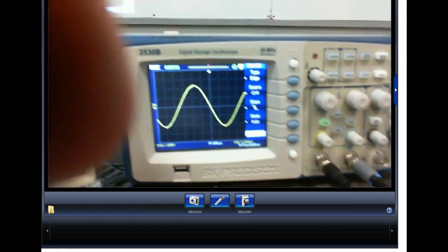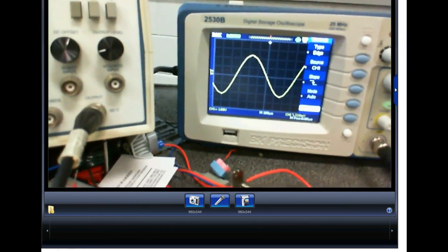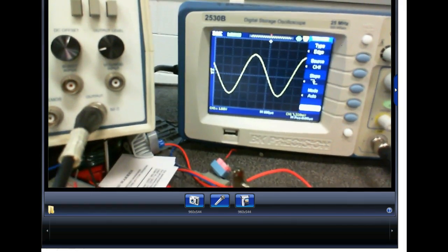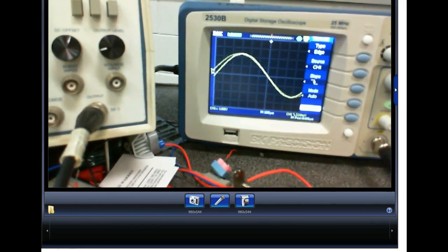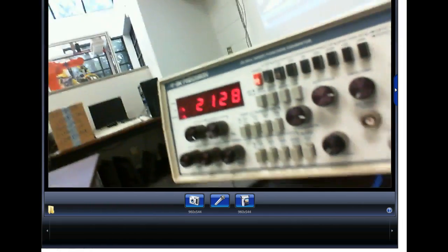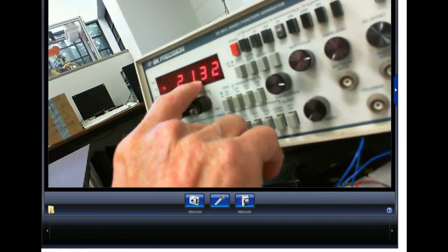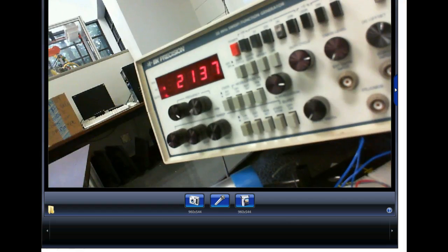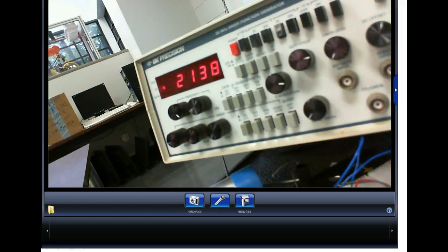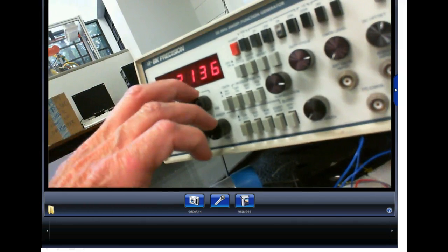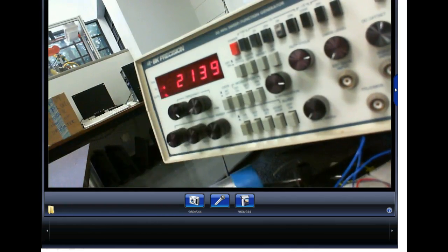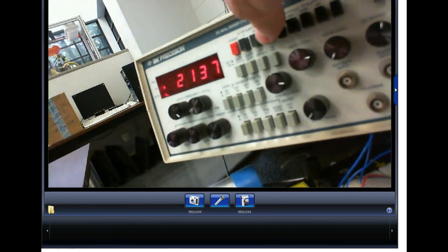But you notice the oscilloscope changes instantly. So you can see it change instantly. But the frequency generator is okay. I wish we didn't buy them with these things. I mean, the frequency counter, I wish we didn't buy them with these. Normally when we teach AC, we tape them over, because what we want people to do is learn how to measure the frequency on the oscilloscope, instead of on that thing. But y'all more than welcome to do that. Fine adjust, coarse adjust, so you can get this thing pretty close to any frequency you want.